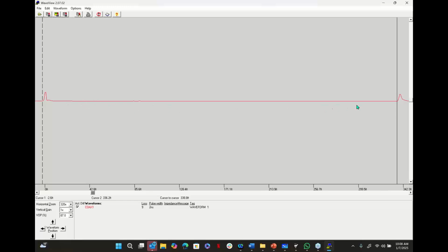As you can see, this line is perfectly flat, which might indicate there's nothing wrong with that cable, but that's before we start to analyze it. You can see that my vertical gain is all the way down, so let's just slowly start to increase the vertical gain. Now, whether you're connected live or you're looking at an uploaded waveform, a stored waveform, or an uploaded waveform on your smart device or your computer, I want you to resist the temptation to just start cranking the vertical gain and zooming in because you might start to miss stuff. So I want you to go slowly.